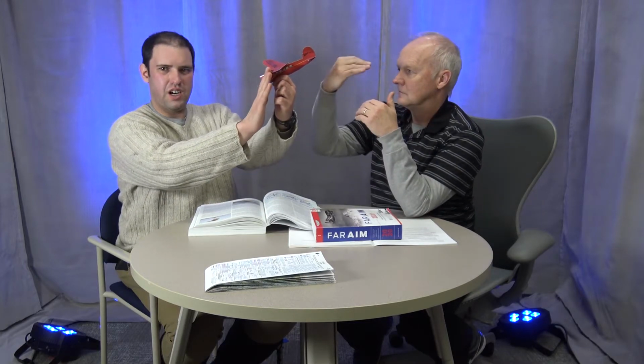You have to give the wind time to catch up. Exactly, because the airplane has mass. It can't change direction instantaneously. So in order to change direction, it has to push on that air, and the harder it has to push on that air, the more angle of attack it takes. So you can actually stall an airplane pointed straight down, which is something that you probably yank the stick back too fast and it'll do crazy things on you. You probably won't experience that firsthand unless you do aerobatic training.